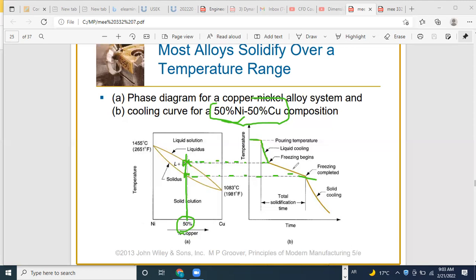When you have an alloy, you don't have a phase of constant temperature, but the change of slope marks the beginning of freezing, because in liquid cooling the decrease of temperature with time is much faster, while during change of phase, from liquid to solid, the slope of variation of temperature is reduced, and it takes a linear profile.